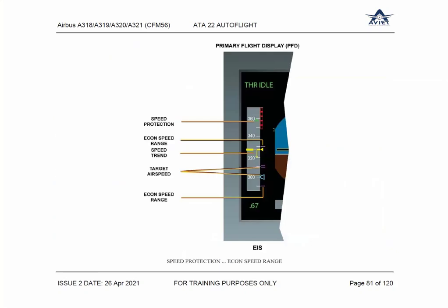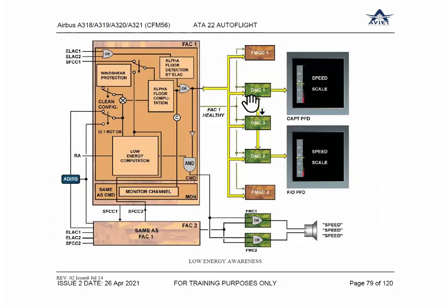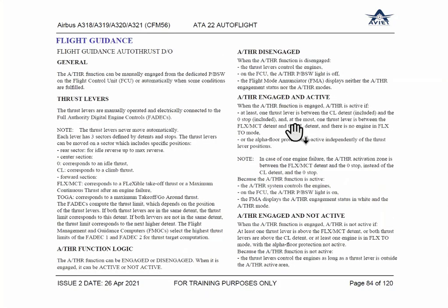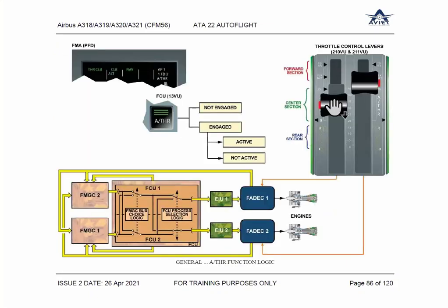Clear, guys? Yes, clear. So just wondering, in case the aircraft is asking for more power and the thrust lever is somewhere down, it won't be a good situation, right? Yes, you are right. But the maximum thrust required during climb and change of flight level, climb is okay. Climb thrust is sufficient. Unless you are going for escape maneuvering and want more power, then he has to go manual. In auto thrust, he cannot.